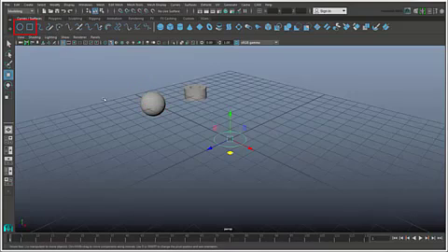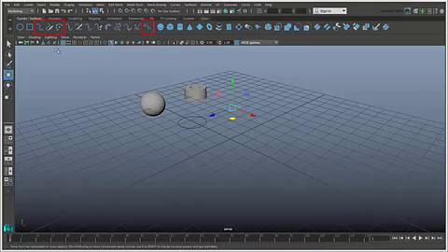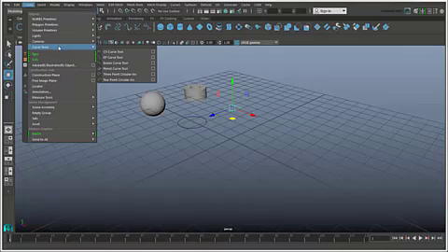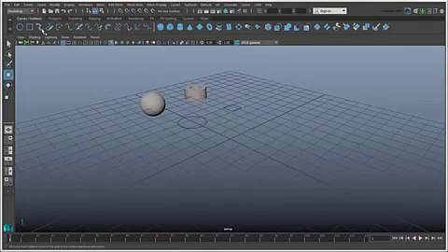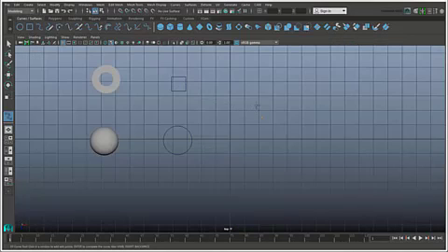Since there are only 2 primitive curves, you usually end up drawing your own. To draw a NURBs curve, click any of these icons, or choose from the Create Curve Tools menu to draw the curve in different ways. We'll click the EP Curve icon, which draws the edit points where the curve passes through. Start clicking in a view, such as the top view here, to draw edit points on the curve, and press Enter to finish.